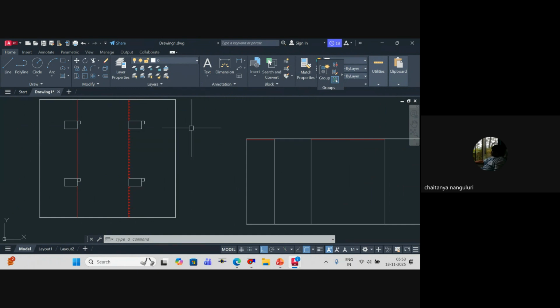We'll try to utilize this because obviously you can even do compartments by keeping a continuous one also, but that will increase your flow rate and water demand. So cleverly, if you have some physical wall which already has a fire rating, you will utilize that wall to reduce the number of nozzles. Am I clear? Yeah.